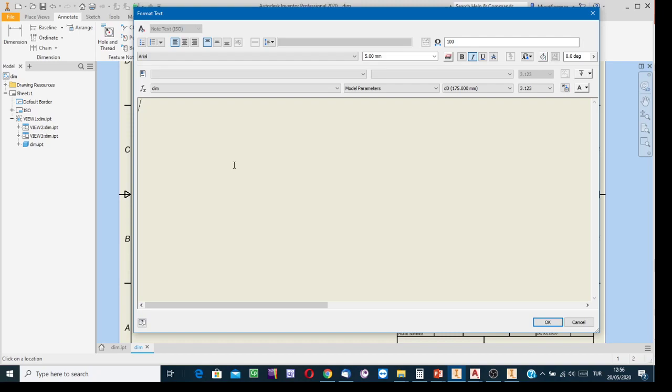I remember the size. Okay, well, first diameter symbol. Drop the list of the symbols, clicking on this listing arrow, and then find in the list diameter symbol. And then diameter of the drill, it is 20. Click on comma. Drop the list one more time and find counter bore symbol. And then from the table diameter symbol, bore diameter is 30. Clicked on comma.